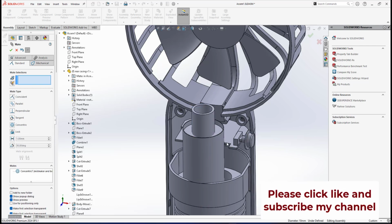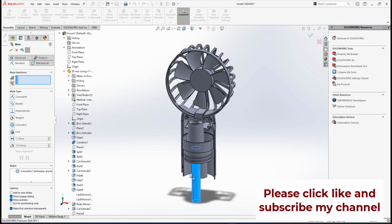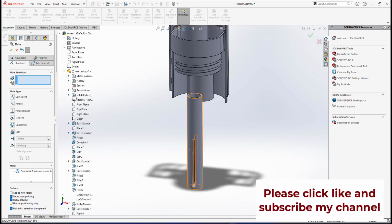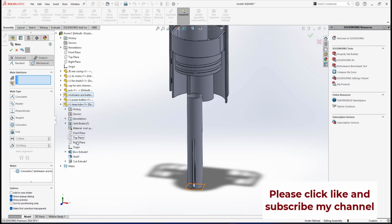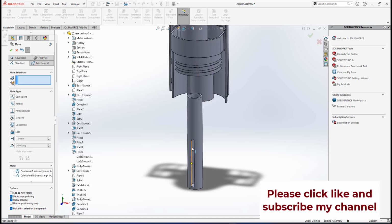In position like this, I can drag this tube for the straw like this. Then I can drag it downward. If you look, the orientation of the slot is not in the right orientation. So what I will do, my second setting, let me close down this. The right plane of the straw tube will mesh with the rear casing right plane.